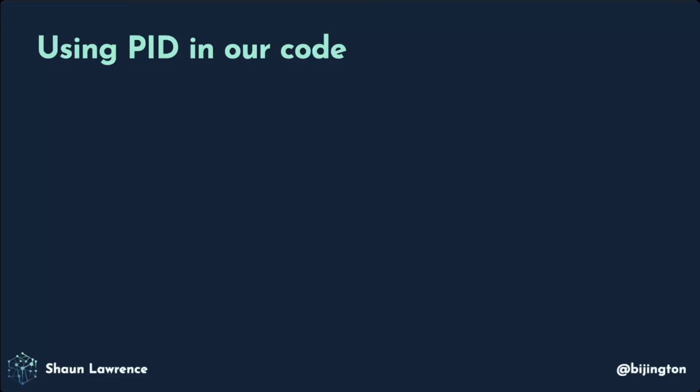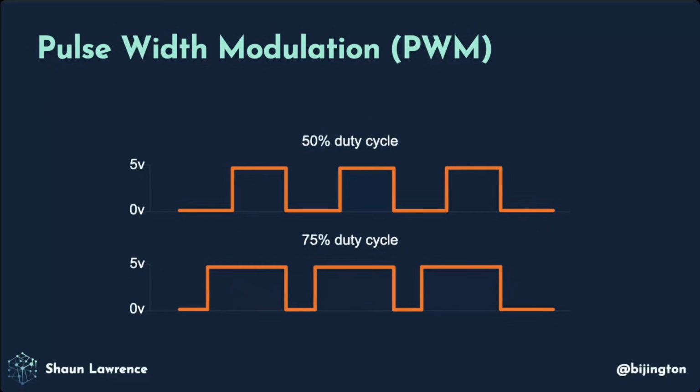So what we can do is use another piece of technology, which is called pulse width modulation. And this is actually how LEDs remain bright without burning out quickly. And in fact, if anyone has taken a photo and seen dark horizontal lines, this is caused by interference between the frequency at which the light is oscillating and the speed of the rolling shutter in the camera.